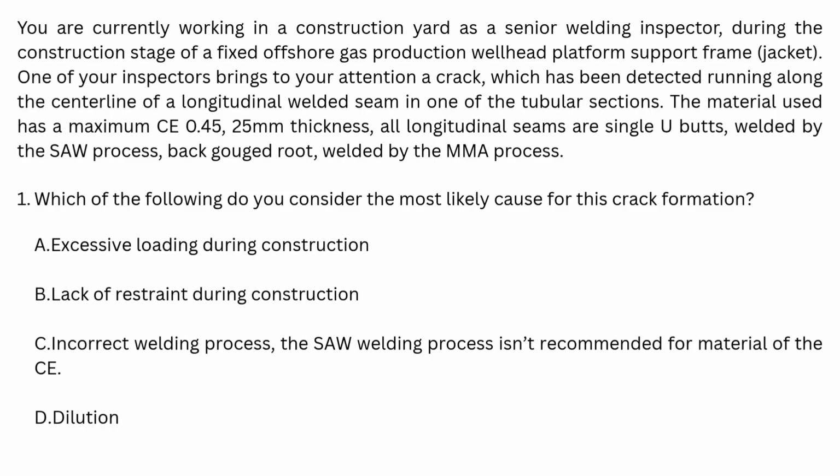You are currently working in a construction yard as a senior welding inspector, during the construction stage of a fixed offshore gas production wellhead platform support frame, jacket. One of your inspectors brings to your attention a crack, which has been detected running along the centerline of a longitudinal welded seam in one of the tubular sections. The material used has a maximum CE 0.45, 25 mm thickness. All longitudinal seams are single U-butts, welded by the SAW process, back-gouged root, welded by the MMA process.